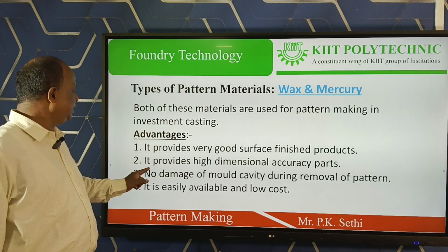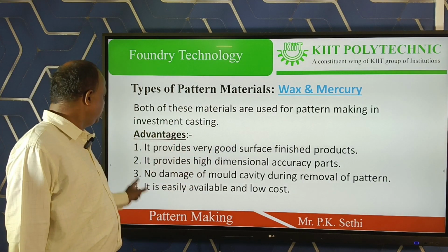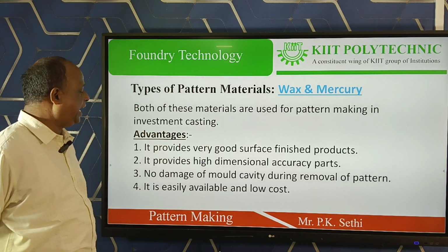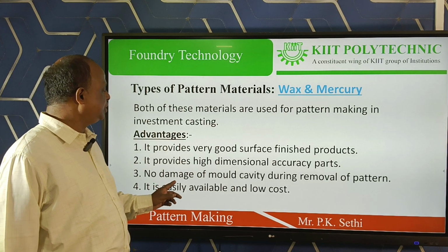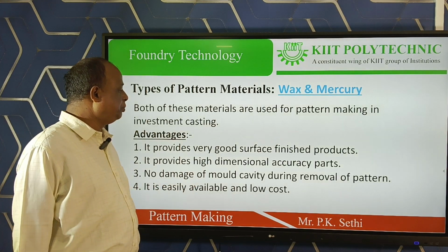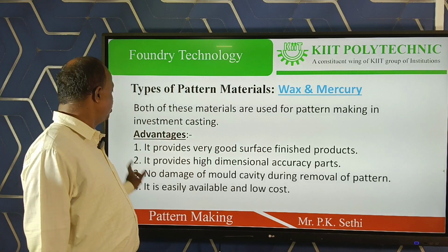So these are the advantages. It provides a very good surface finish. Number two, it provides high dimensional accuracy parts. Number three, no distortion of the mold cavity during the removal of patterns. And fourth, it is easily available and low cost.